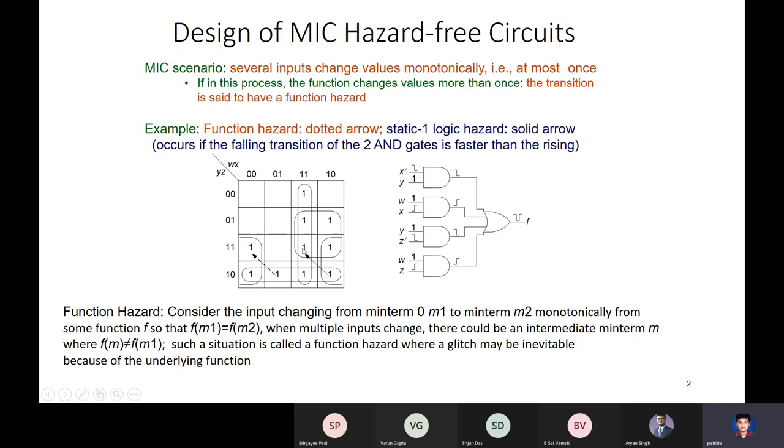From the starting and the ending, you find out which of the bits are constant, they do not change, and then form a logic expression for those bits and get the corresponding cube. For example, here you see W doesn't change, and Y doesn't change. So WY is the constant part. So this cube covering these four things here would be called the WY cube, which corresponds to enclosing these four 1s, and would be called a transition cube. Okay, also you have seen the formula, it's easy to do that.